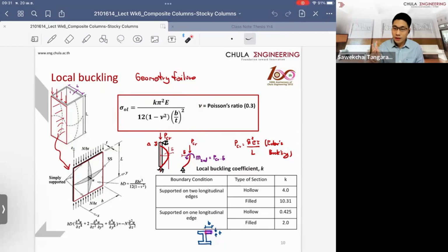We have two types of buckling. One is local buckling. This is caused by the slenderness of some part of the cross section, and it means the cross section doesn't develop the full effective strength, and we have to do some other modification in reducing the width of the cross section, for which we have an approximate method.